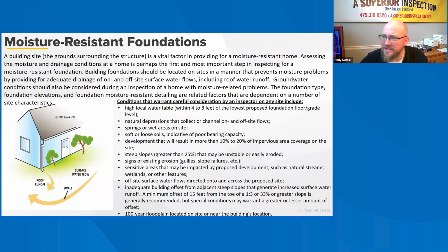So that being said, when the house is built, a site plan should be developed to do more than just locate the building and the utilities and demonstrate compliance with setbacks and other zoning requirements. The site plan should also account for a drainage plan that indicates the slope of the land and the drainage patterns that convey surface water from the building site. For sites that generally provide natural drainage away from the building location, the main concern is establishing an appropriate foundation elevation to maintain drainage immediately adjacent to the foundation.